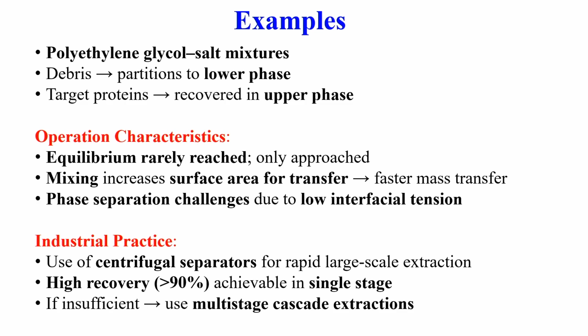There are some examples here, like polyethylene glycol and salt mixture. Debris partitions to the lower phase and target proteins are recovered in the upper phase. What are the operation characteristics? The equilibriums are rarely reached, they are only approached. So, one needs to go for multiple stages, and mixing increases the surface area for transfer.